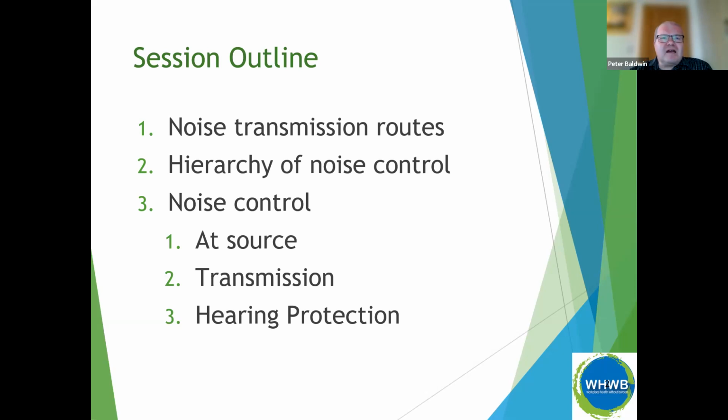And then just look at some forms of noise control. Just mentioned at source, so reduce the amount of noise that's being produced by the machine, etc. And then adjust its transmission routes. And then hearing protection. Hearing protection tends to fail for various reasons. And also, if you're not wearing hearing protection, there is no protection. So it requires a great deal of management.